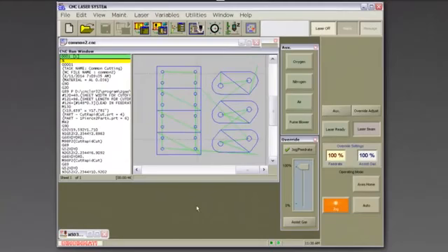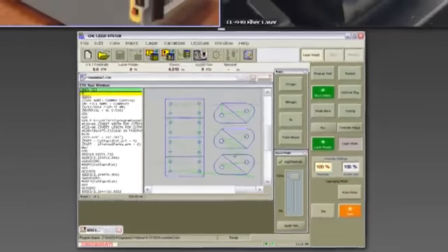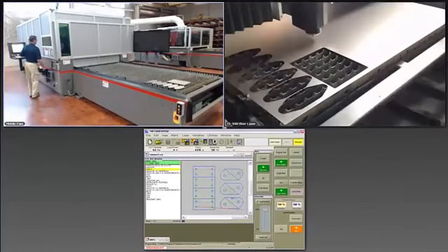The third nest is the common line cutting. On the left here is what Scott referred to as the rapid cut, and on the right is the one pierce two parts. We threw this into one nest so that it would go ahead and cut, but it will give you an idea. It's going to cut everything on the left first, and it will cut the 6 parts on the right.